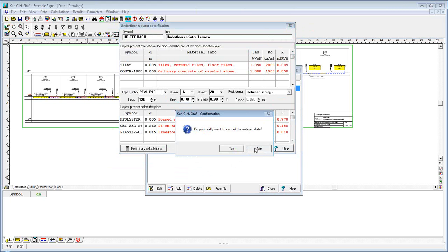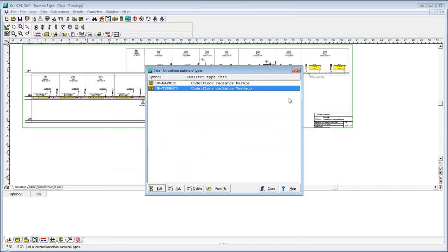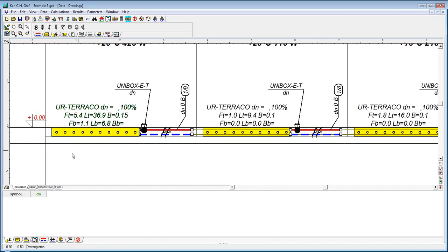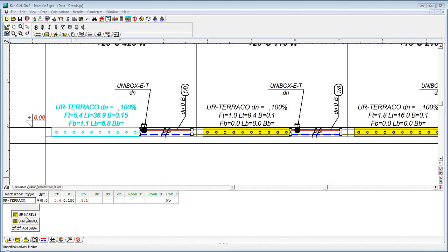And later on we draw these radiators in our diagram. As you see, you can even mix them with the normal radiators. And then in a very similar way, like you enter the data for the convection radiators, you can also choose the type of our radiators, choosing between these types that we have entered in the previous step.